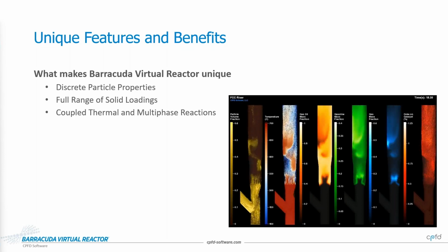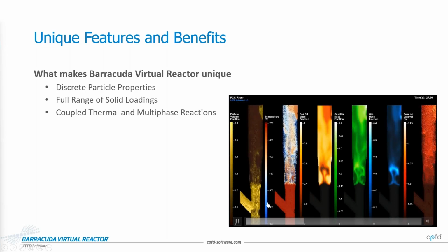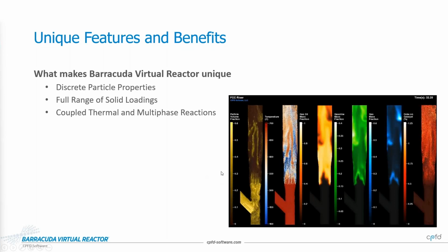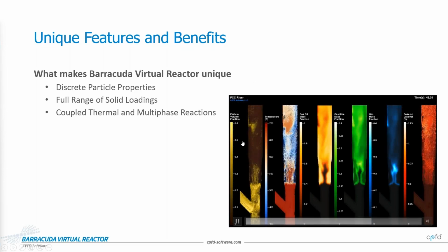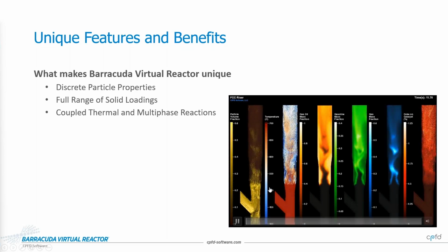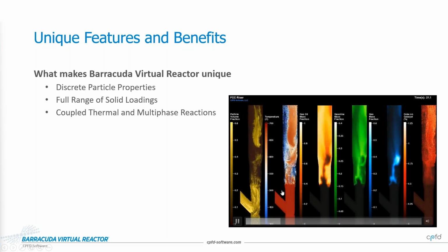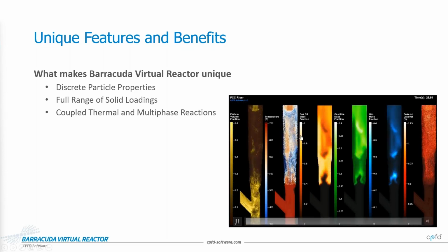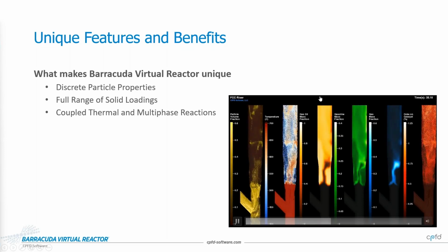And that hydrodynamics is coupled with the heat transfer, the multi-phase reactions. Here's an example from an FCC riser where you have regenerated catalysts coming down, going through a dense phase lift, and then very rapidly moving up where you have the hydrocarbons being sprayed in. Here's the heat transfer, so you have the thermal behavior. Here you have the hot regenerated catalyst getting impacted by the cool feed that vaporizes and the cracking reactions, cooling as it goes up.